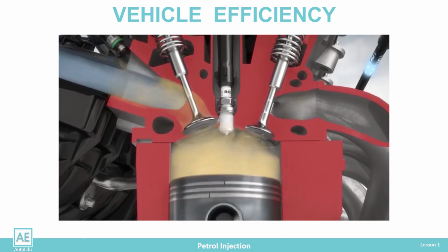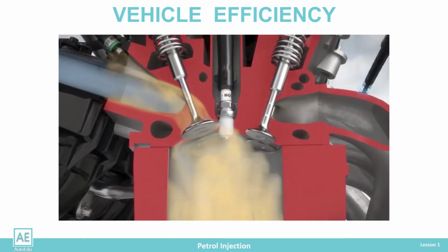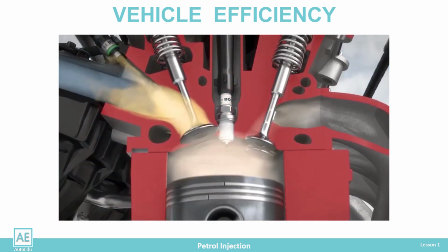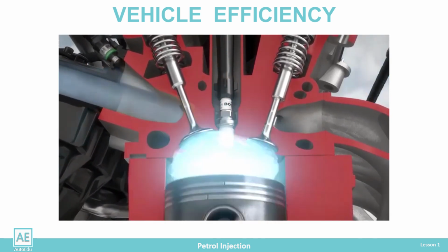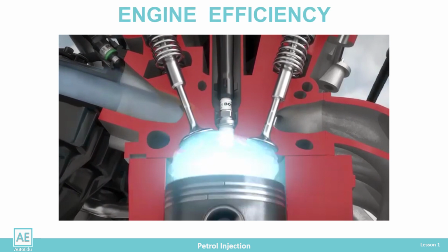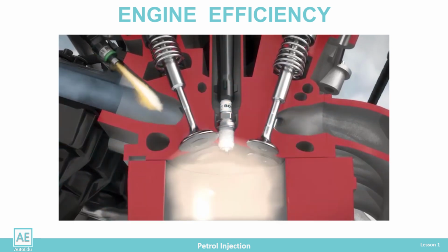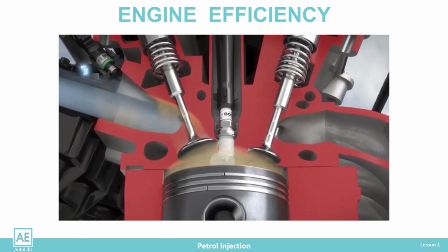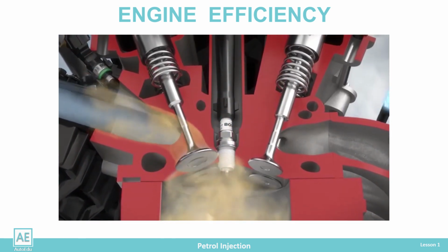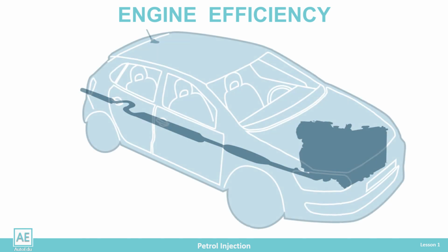Petrol engines are internal combustion engines that convert fuel energy into mechanical energy in thermodynamic processes. The spark ignites the mixture of fuel and air. Combustion inside the cylinder rapidly increases the temperature up to 3,000 degrees Celsius and the pressure up to 50 bar, which is used to push the piston and create mechanical energy. However, the temperature is too high and can quickly destroy engine parts. That's why there is an efficient cooling system that lowers the engine temperature to 100 degrees Celsius.